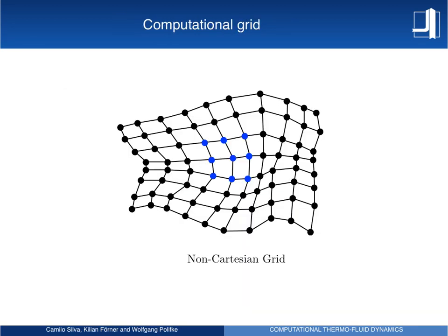This is the kind of mesh we will actually consider this time. Okay, so I just did it somehow very deformed so that you realize what we are actually looking at, aiming at. And we will consider this kind of situation. So we are sitting inside a control volume in here, and we actually express our differential operators, derivatives, Laplacians, with respect to the neighbors, which are actually in this case 3, 6, 8 nodes. Okay,